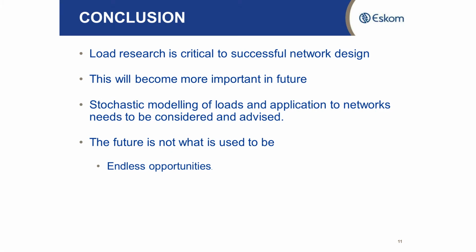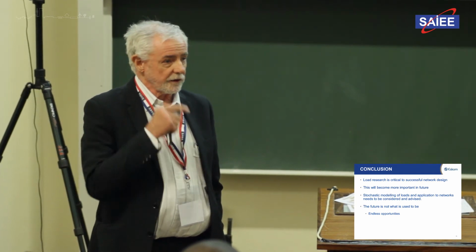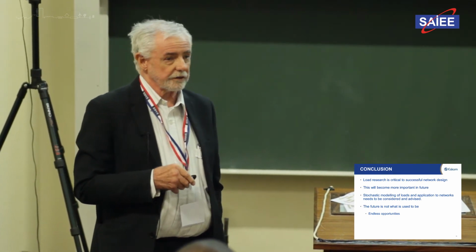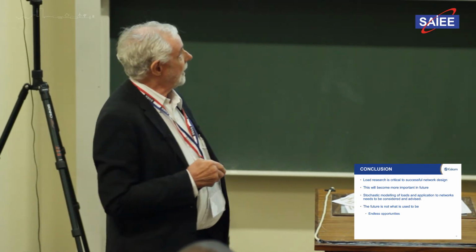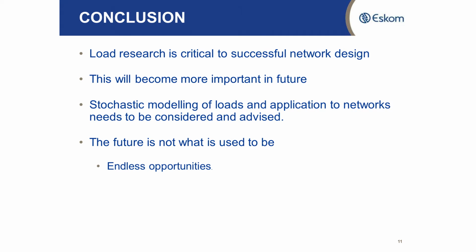So just in conclusion, load research is still critical to your successful network design. Without knowing your particular loads, where those loads are, what the profile of the loads are, what their distribution is, so that you can get your correct diversity, you can't really do a decent network design. And this load research now will become more important because of the variation that we're going to bring in due to distributed energy resources, electric vehicles, and other things coming in.